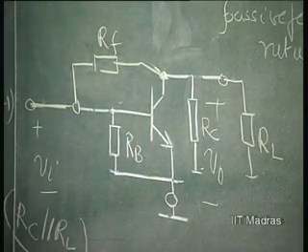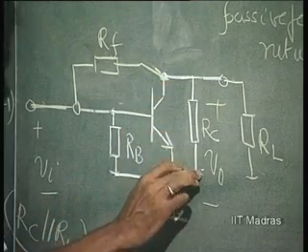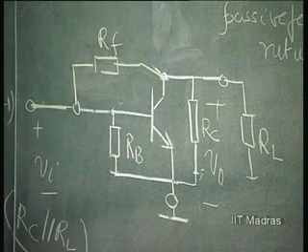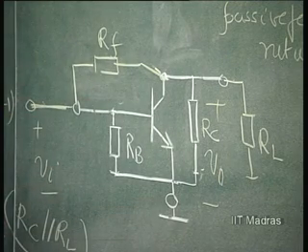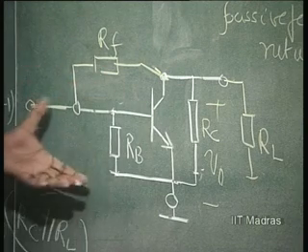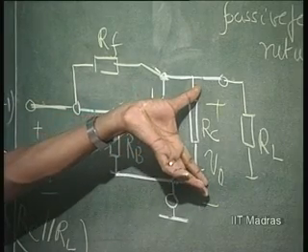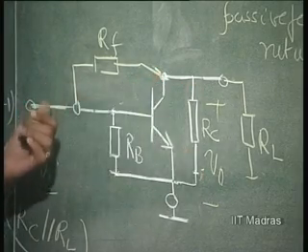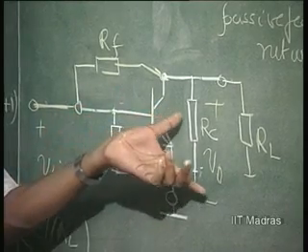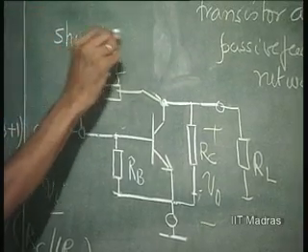That is the amplifier now, simply we will ground this, and this is the feedback network, that is the load. So, how is it at the input, how is it at the output? This is to be understood. I have not disturbed the earlier input voltage, I have not disturbed the earlier output voltage. So, I have connected the output to the input, that means it can only be in shunt at the input and in shunt at the output.